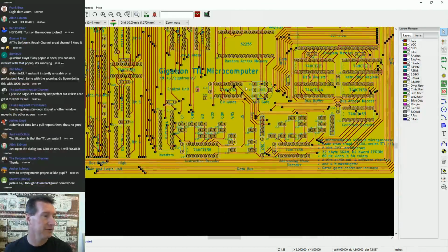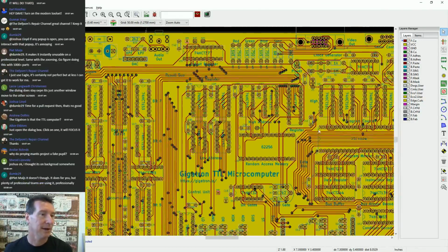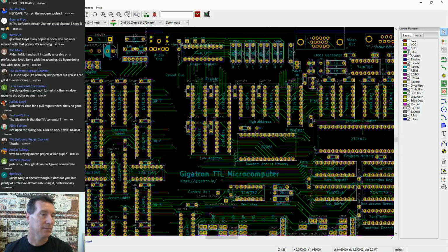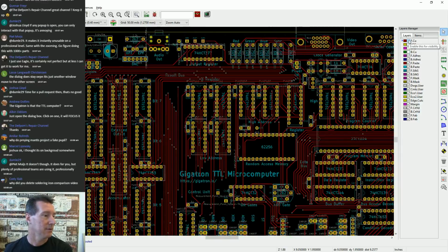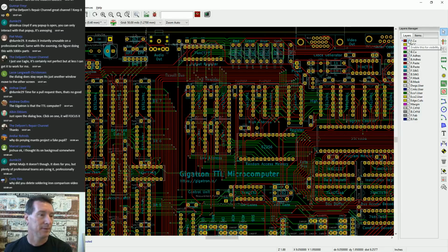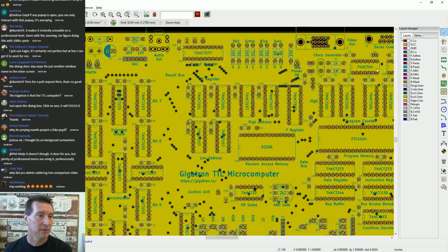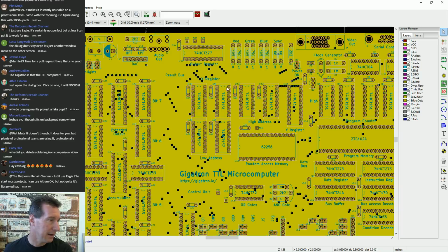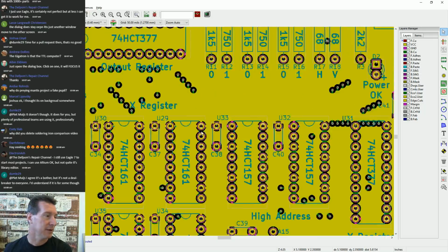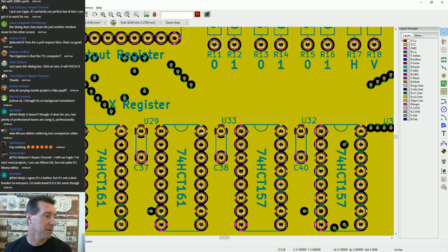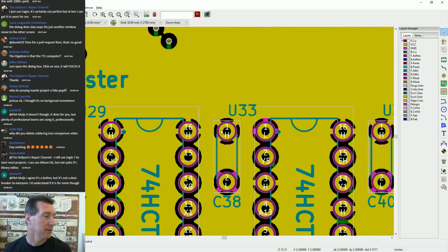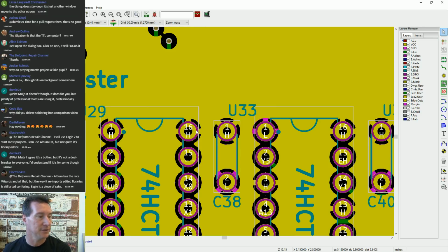Keep clicking the wrong thing to scroll around. So anyway, now we've got our top copper. There's our bottom copper. And we've got our VCC plane, and the thermal reliefs look good. No worries. I can just see them. Sorry if you can't see them. Yep. No problem whatsoever. That's not going to cause a problem soldering-wise. You know, we could, what's the thickness of those? They're like 15 thou traces, 15 thou.